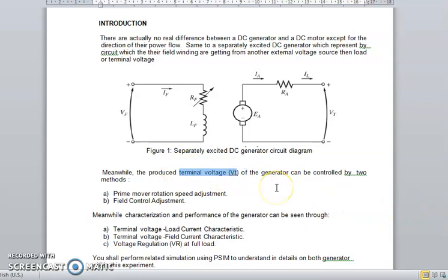That's why we measure the performance of our generator in terms of their voltage regulation. When we tap the terminal output into a load, it produces electrical output. When the load is low, how much is the measured terminal voltage, and when we put the highest current, the rated current load, which draws the current at the rated current, how much has the voltage dropped to. So we compare these two kinds of voltage, the difference. That is the voltage regulation of our generator.